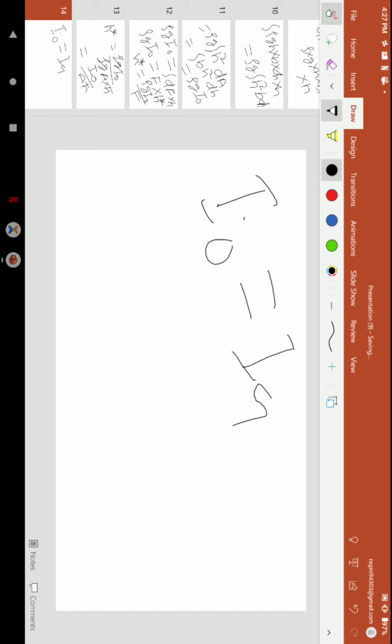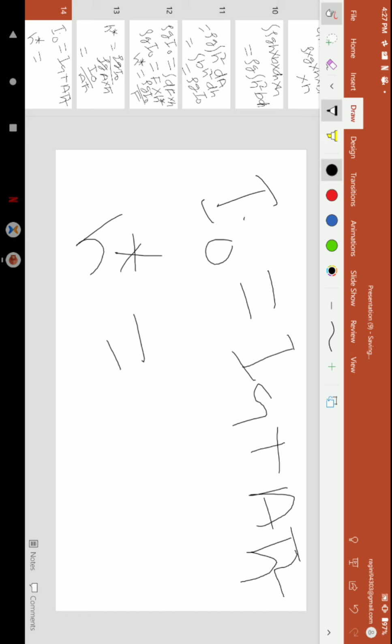I naught is equal to Ig plus A into h bar square. So we have to replace it in the previous equation, I naught divided by A h bar. If we replace I naught with this, then h star must be equal to Ig divided by A h bar plus h bar.